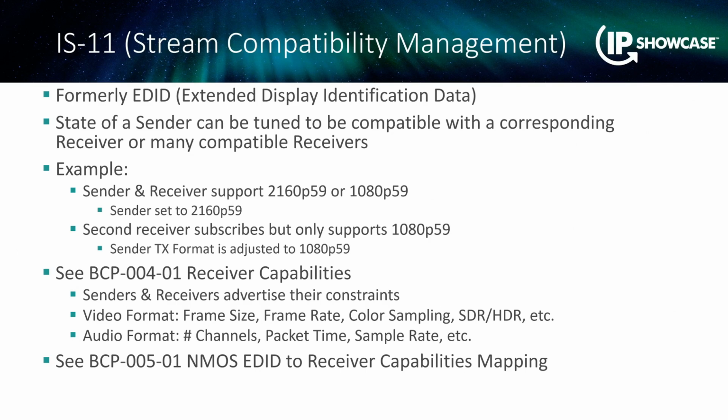And this kind of ties in with EDID as well, so that the 2110 devices will be able to query their monitors that they're speaking to over HDMI. You can't do it with SDI, right? But if you're talking to an HDMI display, you can find out what its capabilities are and present those to the controller, so he can prevent you from doing things you don't want to do.